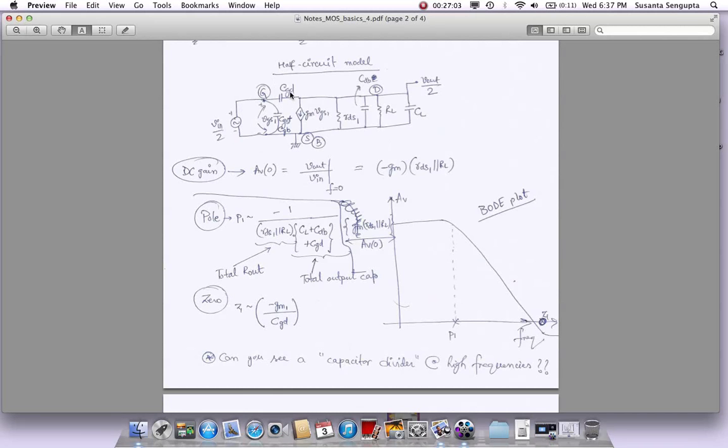If you're trying to find an s-domain transfer function, or in omega, whichever you're trying to do, I can derive it by applying Kirchhoff's current law and Kirchhoff's voltage law everywhere and derive that big equation. From there also, I will be able to find the DC gain, and the poles and zeros, which is what we'll find next. But here I really want you to do the derivation and then compare and see that these intuitive results actually make sense. I'm trying to derive these things intuitively without getting into the complete equations.